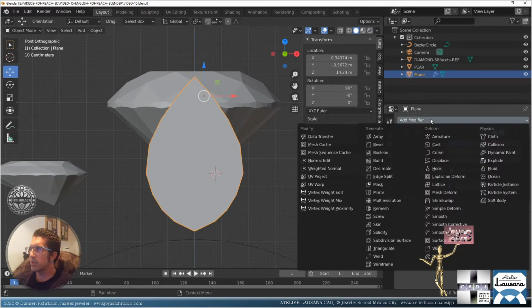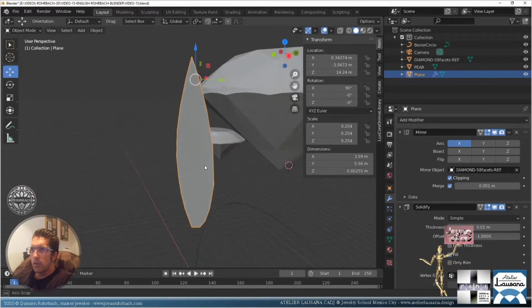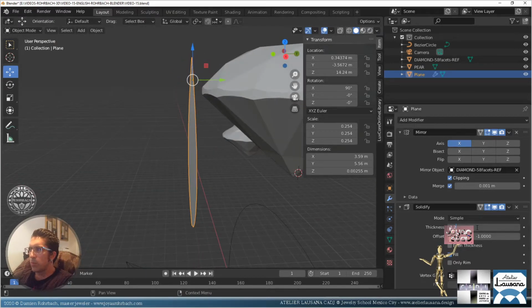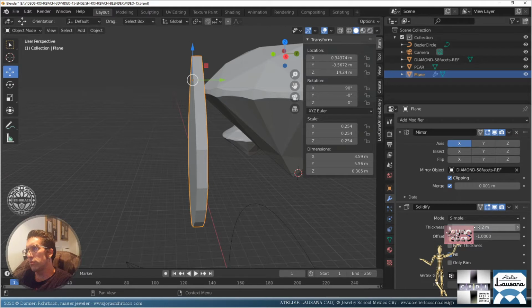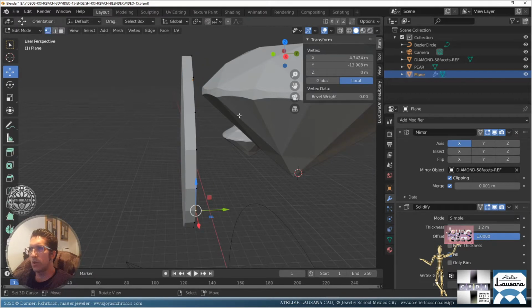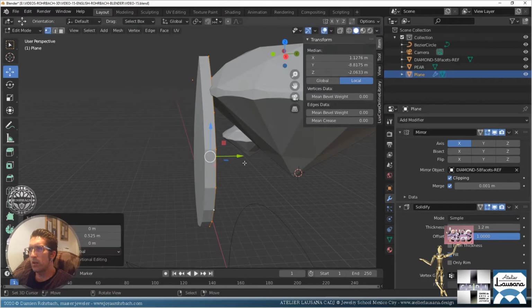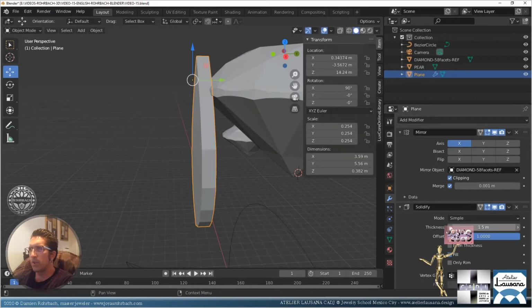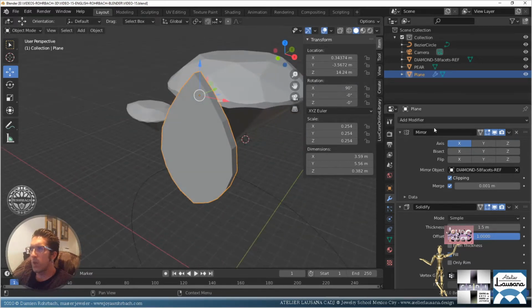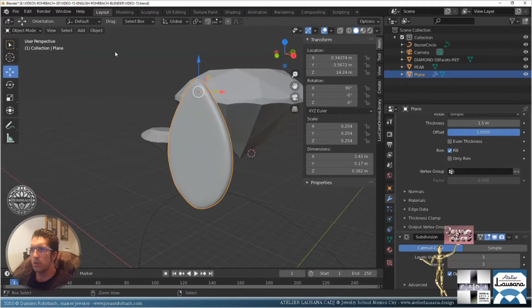Okay, we have this. Let's solidify this. Let's solidify this at 1.2. Direction 1. Okay, so I'm going to take everybody here. I'm going to put 1.5, I guess. All right. It's pretty good. Now let's put some subdivisions. I go to 3. Generally, it's good enough. Smooth.